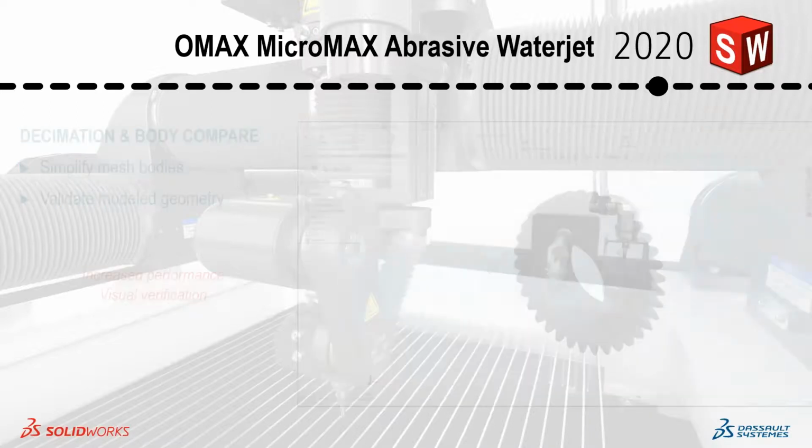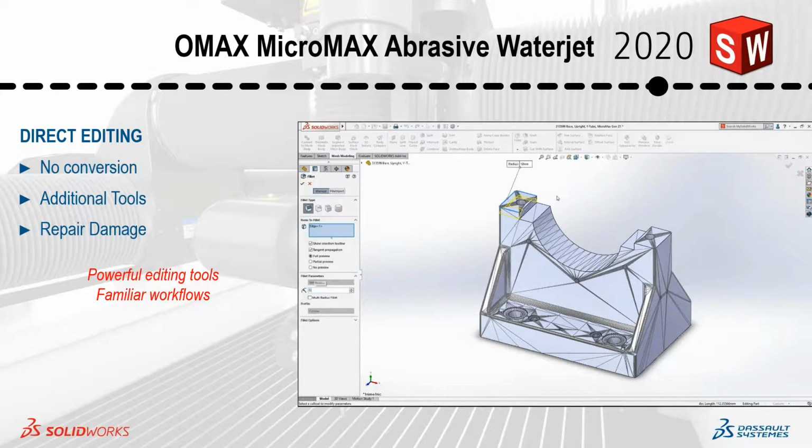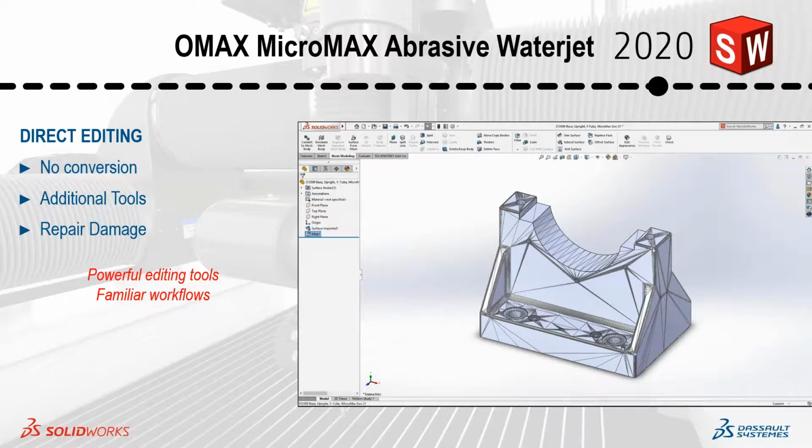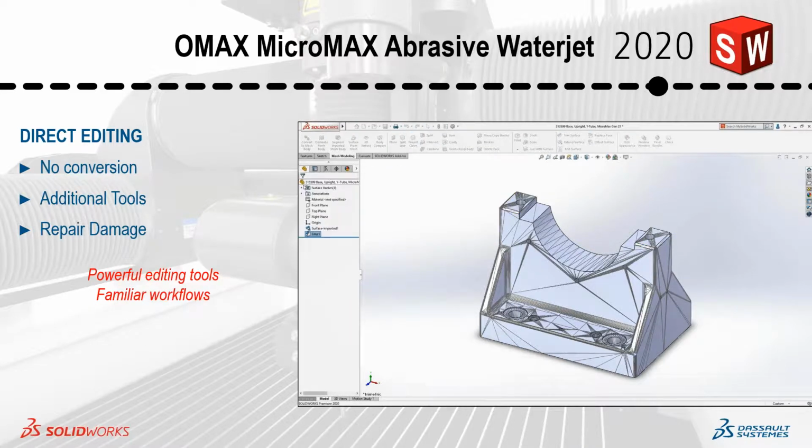So moving on, as I've mentioned earlier, the advancement of technology and the need to edit mesh geometry is becoming more and more common as well. So with SolidWorks 2020, you can now fillet edges like you usually do for your solid bodies, and the fillet can even be changed to chamfer and vice versa. The modification tends to involve dimension change as well, so offsetting surfaces, as you can see in this video, can easily be done on the mesh geometry.